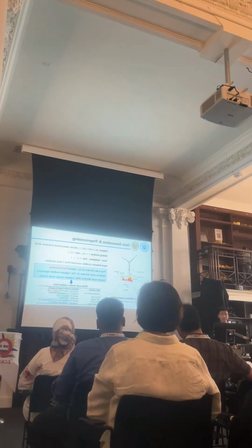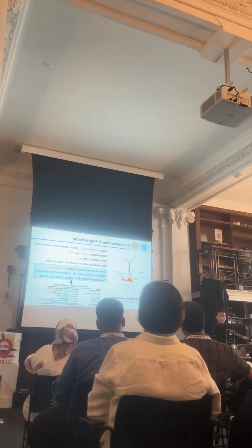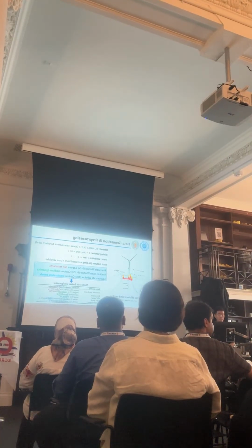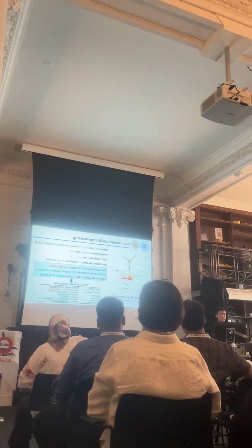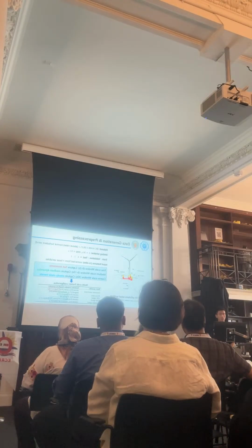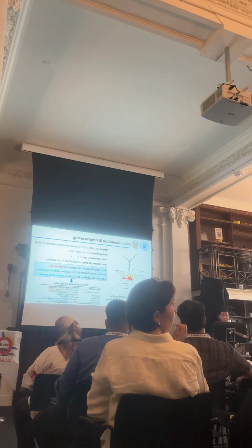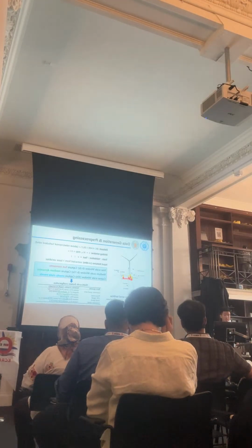Now let's talk about the data generation and pre-processing part. We use the IEA 15 megawatt offshore wind turbine reference model, and the dataset comes from the IEC standard DLC 1.1, which corresponds to normal turbulent wind above the rated wind speed. We use a sliding window of 30 seconds, and we train, validate and test with a time series split to avoid data leakage. Our main innovation here is our multi-scale feature extraction.